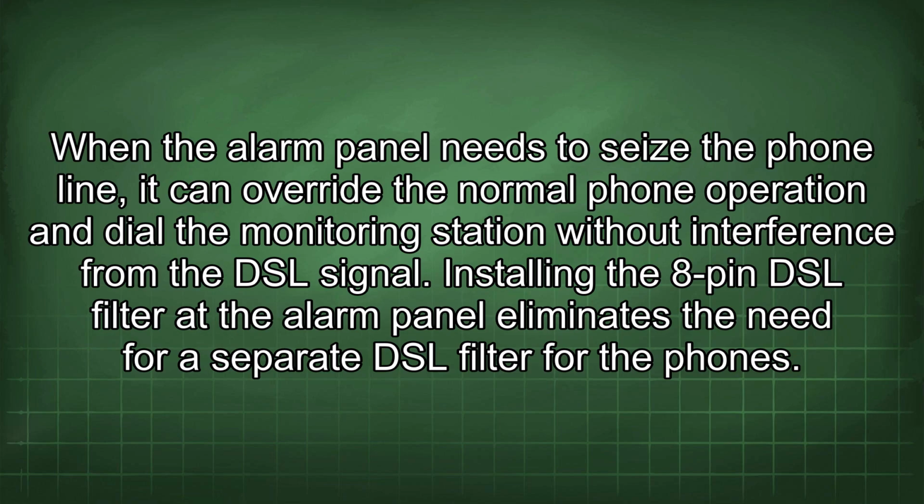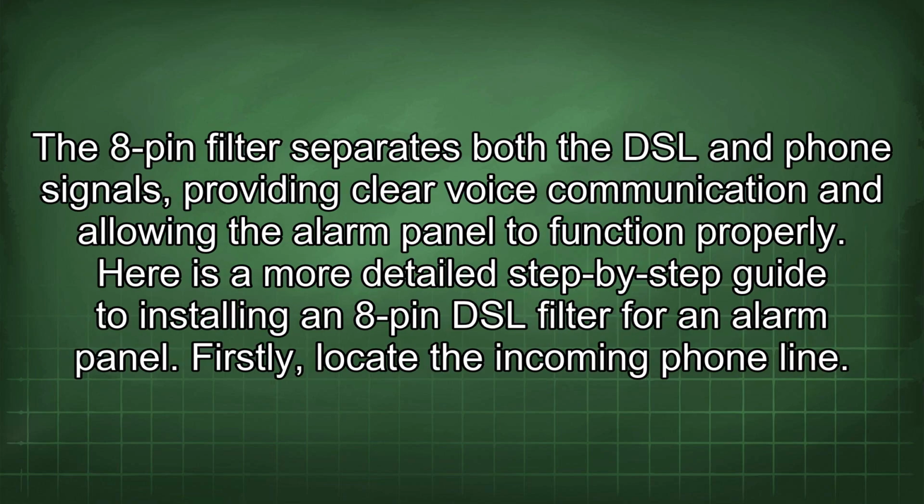Installing the 8-pin DSL filter at the alarm panel eliminates the need for a separate DSL filter for the phones. The 8-pin filter separates both the DSL and phone signals, providing clear voice communication and allowing the alarm panel to function properly. Here is a more detailed step-by-step guide to installing an 8-pin DSL filter for an alarm panel.